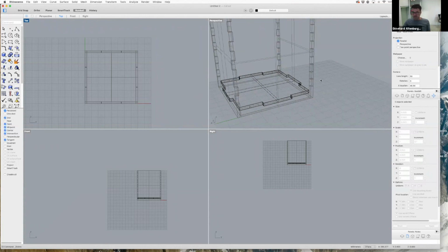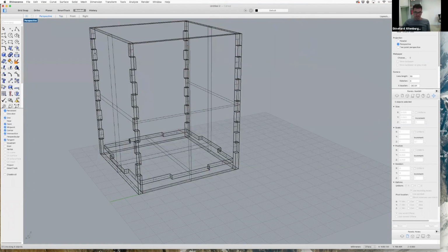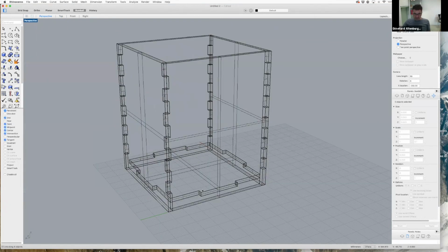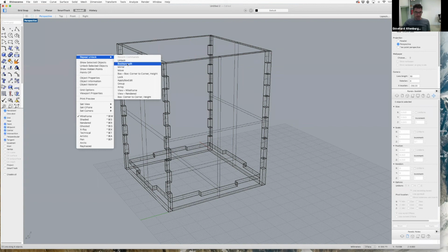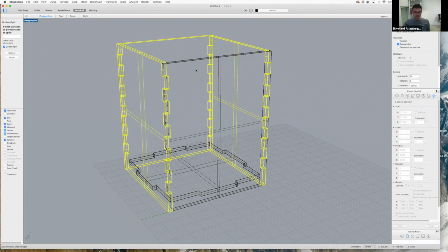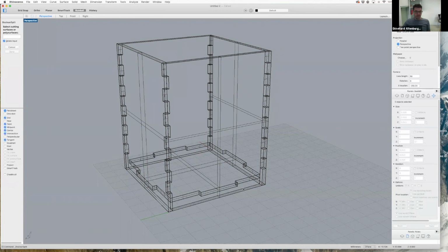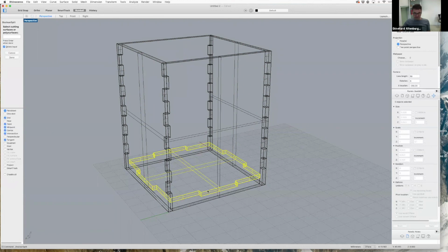How do we do that? We first need to unlock everything. So we press unlock. And now we do again a Boolean split, and perhaps we can do this in the full view. So what we want is this piece that sticks out to penetrate the side walls. So again, Boolean split, select the surface of polysurface to split. So we want the 4 walls. We press done. And now we select the cutting surface, that's the ground floor.